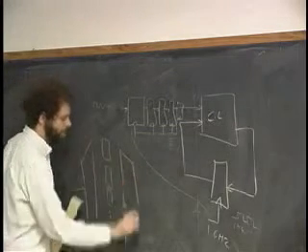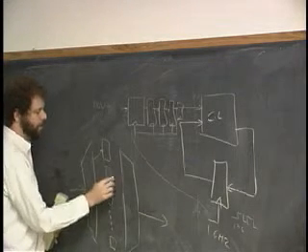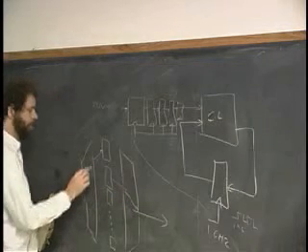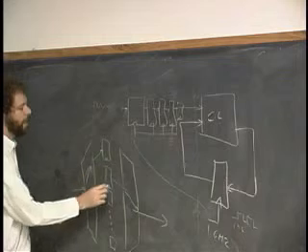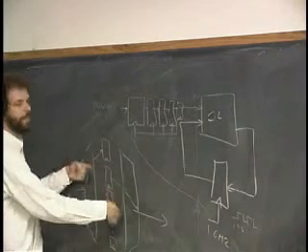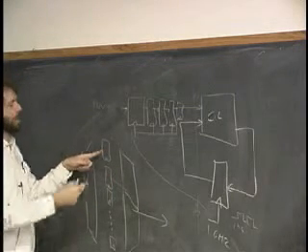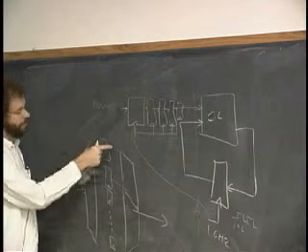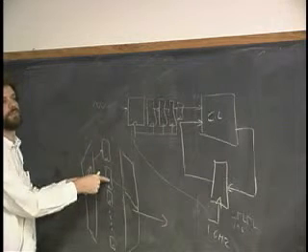and a multiplexer over here, and I can basically be doing a round-robin scheme like this, where these are only clocked at a hundredth of the rate, and I basically go around and around like this, and each one of these takes a part of the job and takes 100 billionths of a second to get this done, but the next job is given to the next one 1 billionth of a second after it's given to this one.